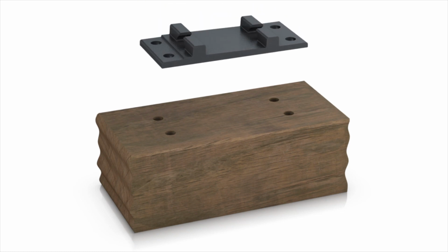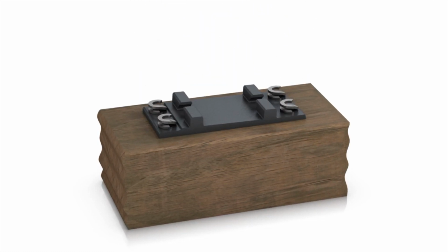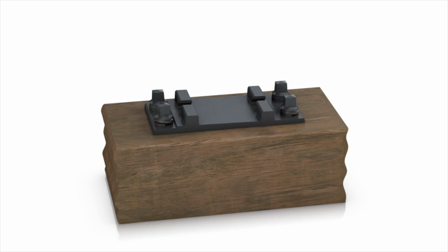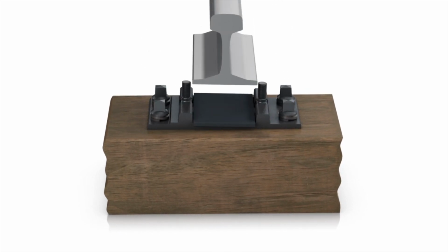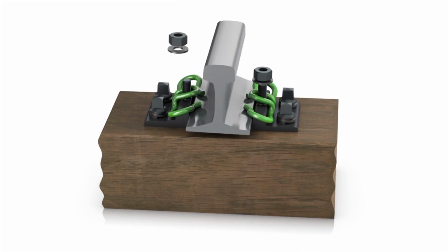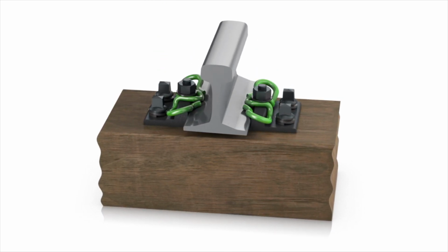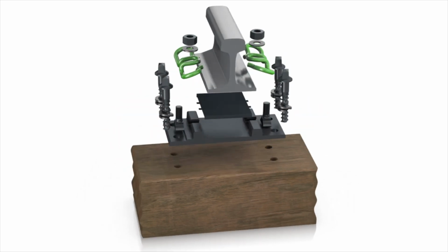Another common type of fastening is used on flat sleepers without angled recess. A base plate with the desired rail angle is anchored onto the flat sleeper. Spring washers ensure a permanent tight fit. A sleeper pad is installed between the rail base and the base plate. The tension clips are bolted on the base plate with the use of T-shaped bolts to ensure vertical stability between the rail and the base plate. This type of fastening is called KS superstructure because its shape vaguely resembles a K. In practice, a multitude of different sleeper fastenings exist according to national industry standards and regulations.